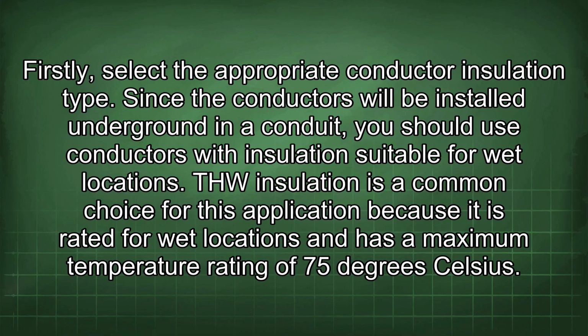Since the conductors will be installed underground in a conduit, you should use conductors with insulation suitable for wet locations. THW insulation is a common choice for this application because it is rated for wet locations and has a maximum temperature rating of 75 degrees Celsius.